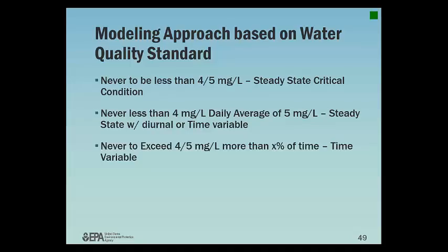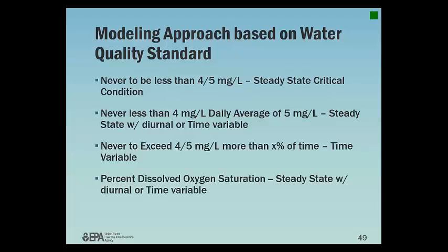Never to exceed a concentration 4 or 5 milligrams per liter more than X% of the time. This would require the use of a time variable model running through a continuous simulation, which will take you through all the various critical, subcritical conditions within the period of time that's being investigated. Percent dissolved oxygen saturation, you could do this either with steady state with a diurnal option or time variable. So you're looking to determine what is the maximum loading that you can have but still achieve a percent saturation.